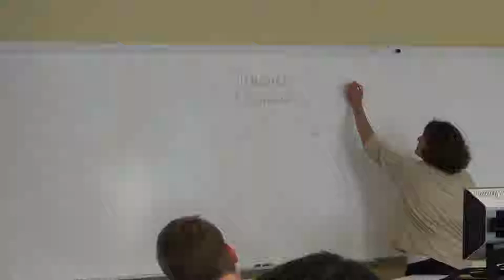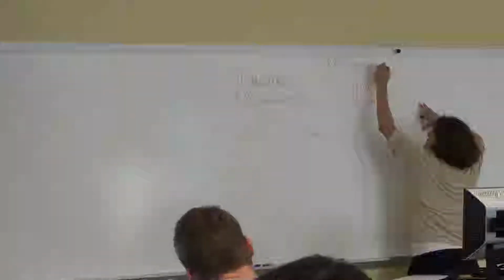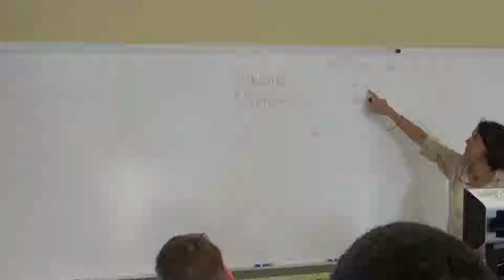What's the unit? Okay, Newton meters. So one example is Newton meters. What's another one? Foot pounds. Isn't this kind of interesting? What do you notice? A moment is equal to a force times the distance, right? Isn't it interesting in metric? We use Newton meter, we put the force first. And in the English system, we say foot pound, we have the distance first.